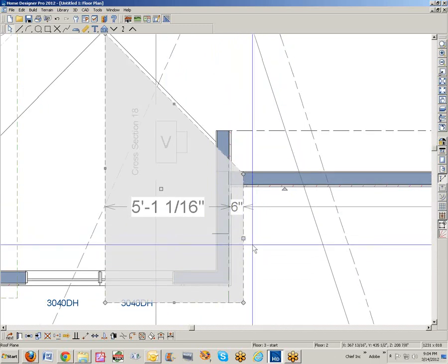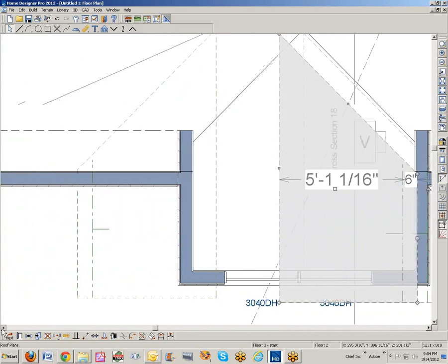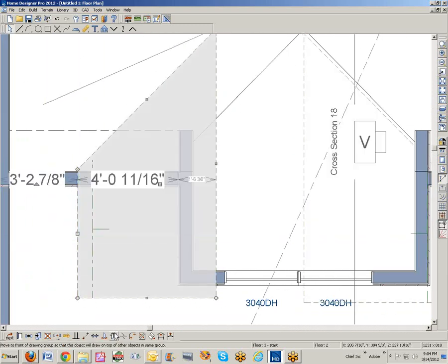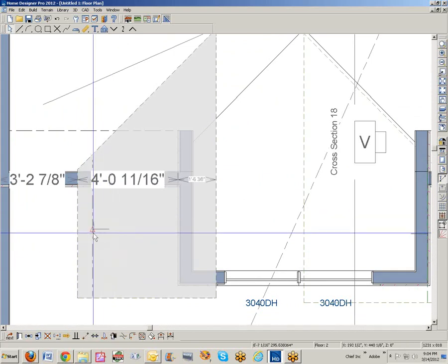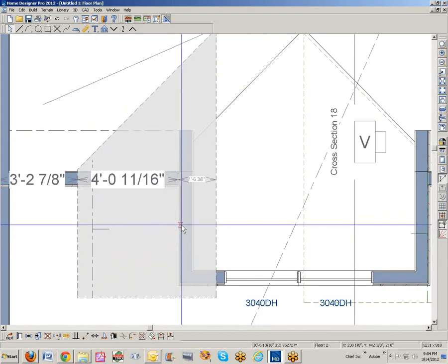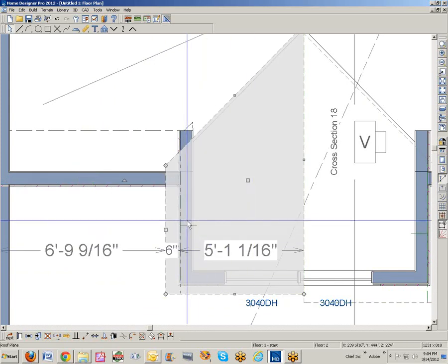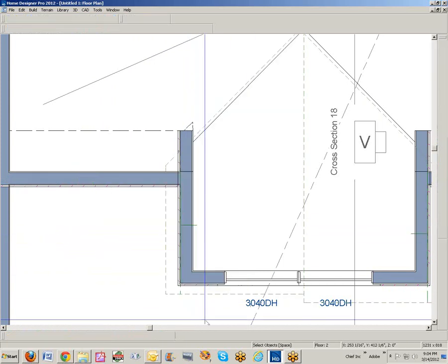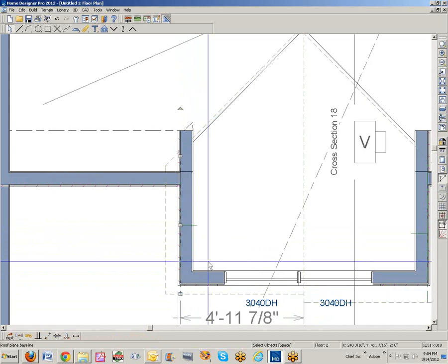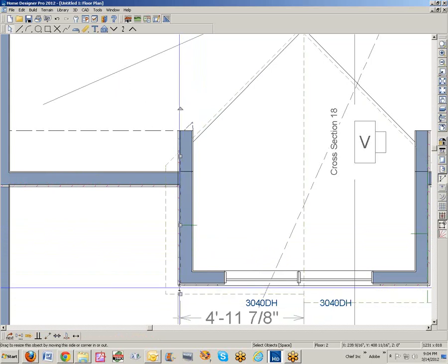I'm going to use the arrow keys, and okay, you can't do that in Pro. You can do it in Chief Architect. Never mind. We'll do the other one. Select the roof plane, point-to-point move tool, left click on what I want to move, left click, and then left click. See that little precursor, that little red hourglass looking thing? That's a precursor, and it lets me know that my cursor is on the edge of something. And see, now that baseline is properly placed. It's a little hanging over here. You can select the things and resize them if you don't want them.